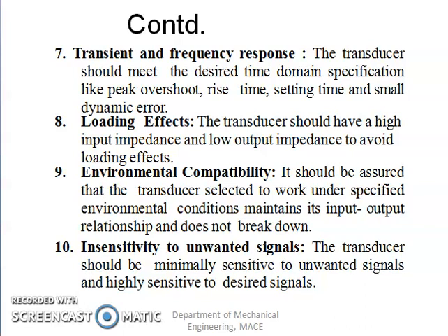Usually a transducer should have high input impedance and low output impedance to reduce the loading effect. So we usually select such transducers. Another factor is environmental compatibility. Normally we select a transducer that can work under specified environmental conditions, maintains its input-output relationship and does not break down.